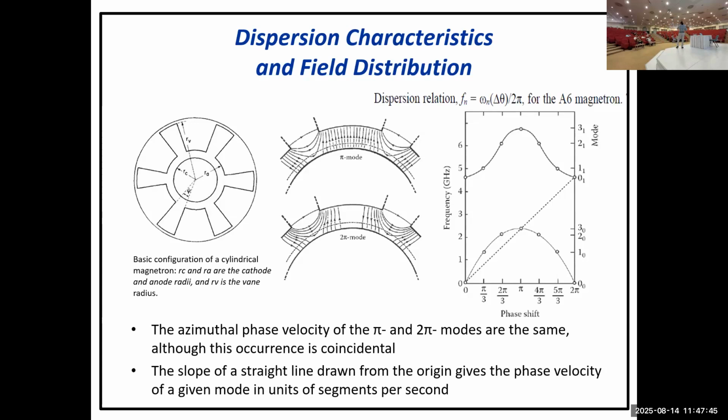If you have 6 cavities, you're going to have 4 resonances: 6 over 2, and then plus 1. If you have more cavities, you're going to have a different number of resonances. For linear devices, when you twist your slow wave structure in the other direction, you will have N plus 1 resonances when you do the cold test experiment, or you do your homework in 3D electromagnetic software.